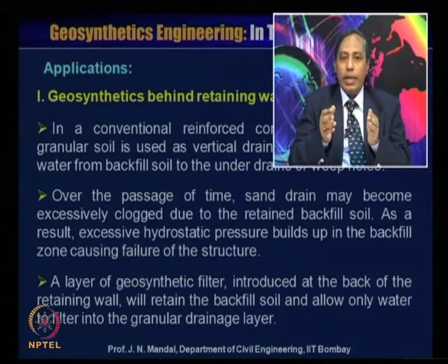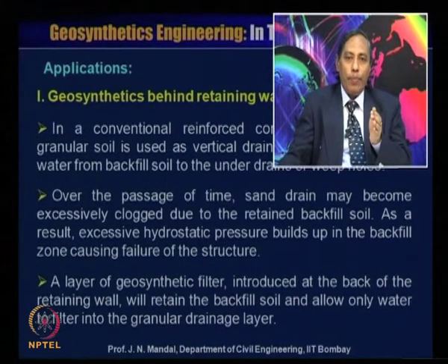As a result, excessive hydrostatic pressure builds up in the backfill zone, causing failure of the structure. A layer of geosynthetics filter introduced at the back of the retaining wall will retain the backfill soil and allow only water to filter into the granular drainage layer.